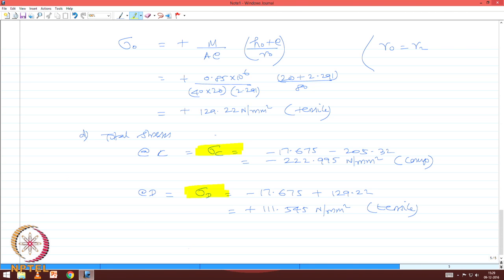So, friends, using the equation derived in the last lectures, one can estimate the stresses at intrados and extrados points for various applications, including the direct stress and the stress due to the moment. One can also easily conclude what is the nature of stresses: one, based upon the sign convention, two, based upon the nature of the moment caused on the curved beam.